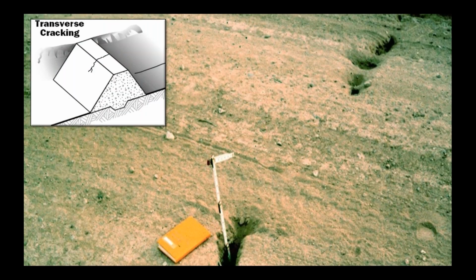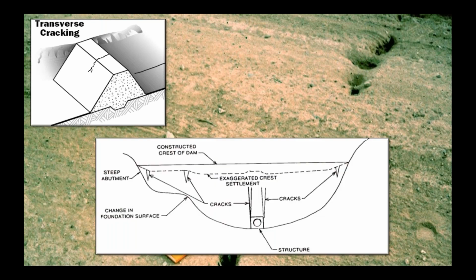Now, then you can also have transverse cracking. Those are more serious because they go upstream to downstream and they can create a seepage path. And there are different reasons why. And I'll just explain a couple of things. One of the reasons why we have so many problems with seepage at the conduit, and that's often the place where the dam will fail.